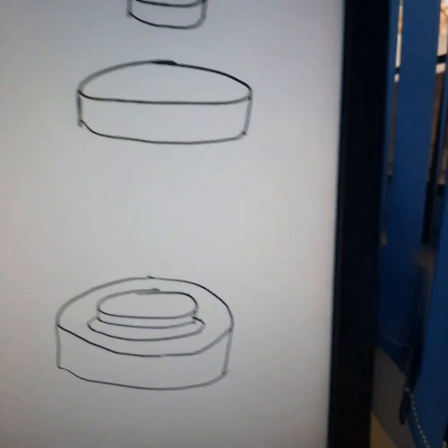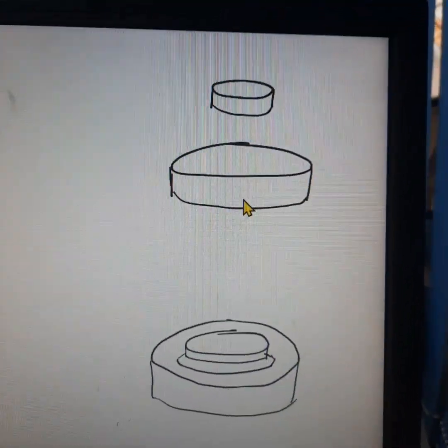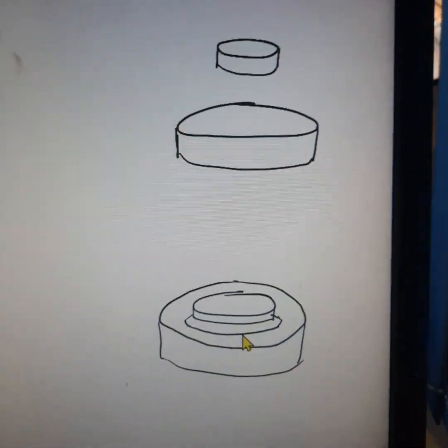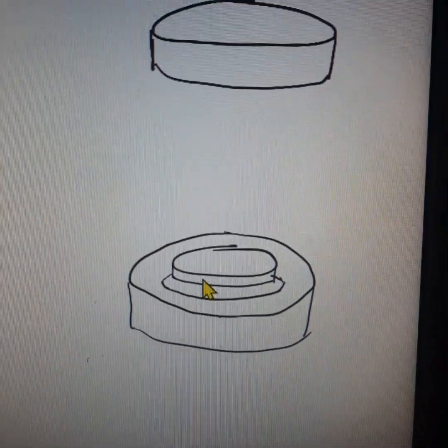Here in this example, there are two circular plates. One is a smaller one, the other one is a bigger one. You want to join these two plates using a fillet weld, as shown in this figure. How to show it in the drawing?